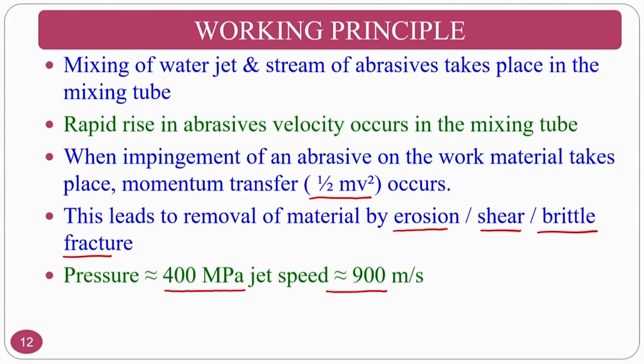While those people who are using this machine, they should be very careful about it, because you close the system, I mean to say you close the doors, then you operate the machine. Otherwise, it will be dangerous whenever the operation is going on. It looks very easy. Sometimes you cannot see the jet also because the water is transparent in color. So, there may be a chance of accident. For that purpose, you should be very careful and close the doors before you start the operation.